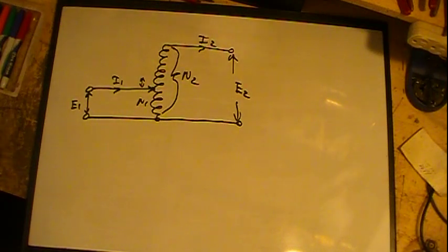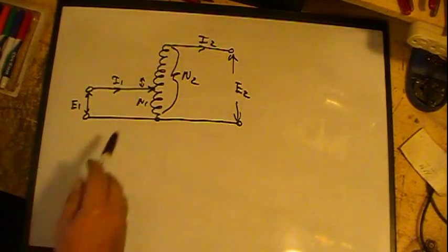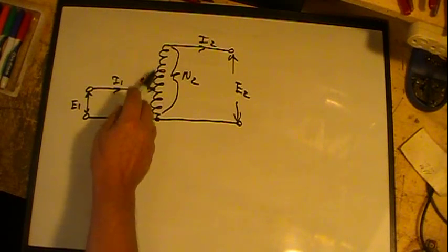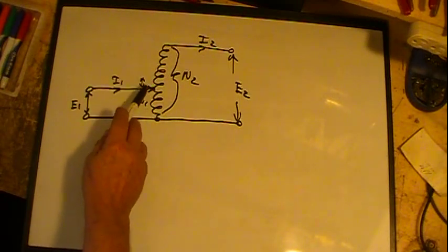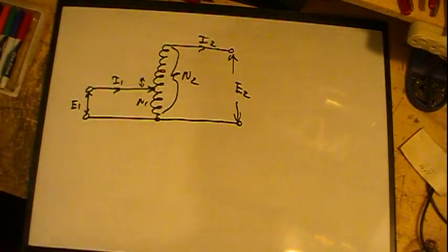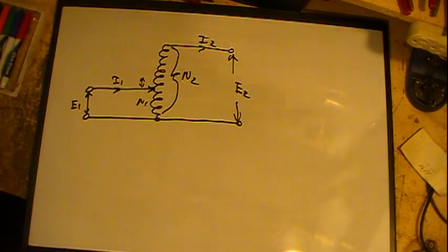That's how come with most variacs you can plug in 120 volts and, depending on the variac, squeeze 130, 140 volts out of it if you crank all the way up, because it's stepping up at that point. You move it far enough, it turns into a step up. Otherwise it's a step down transformer. But it's an autotransformer, no different other than the fact that instead of being stationary, you can actually move this tap back and forth to get your different voltages. But as far as ratios go, it's exactly the same.